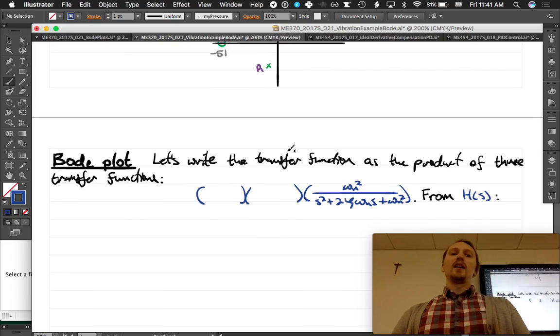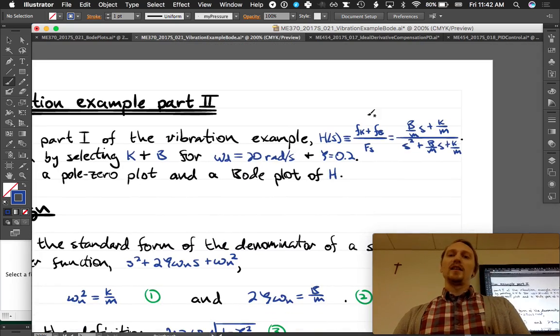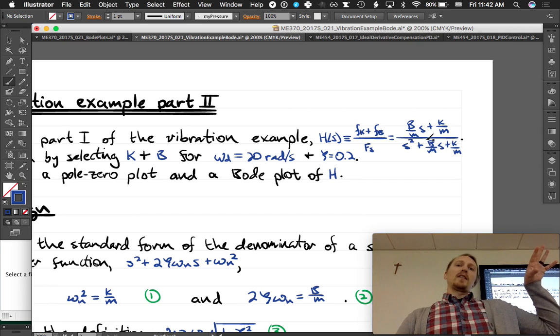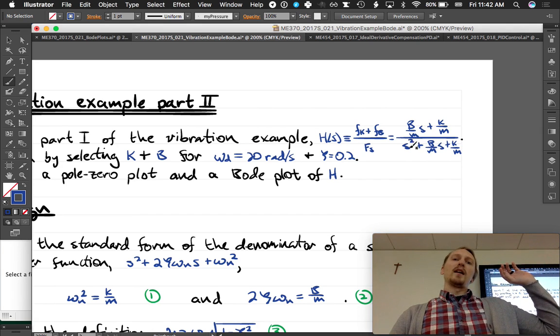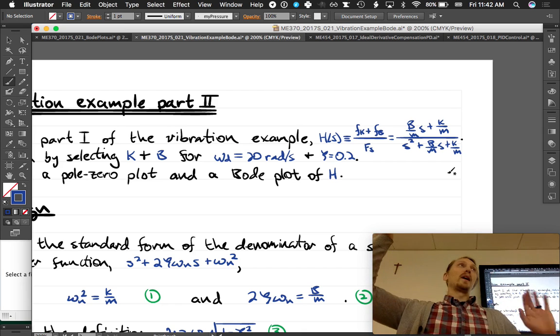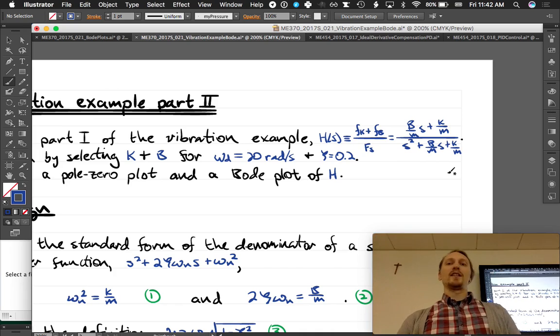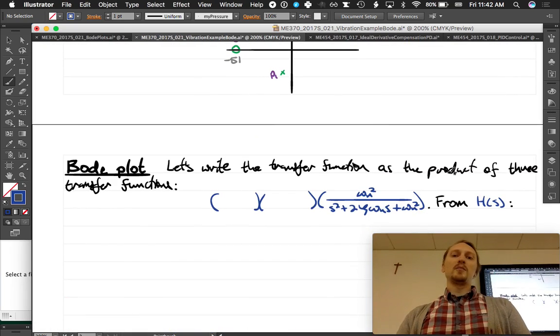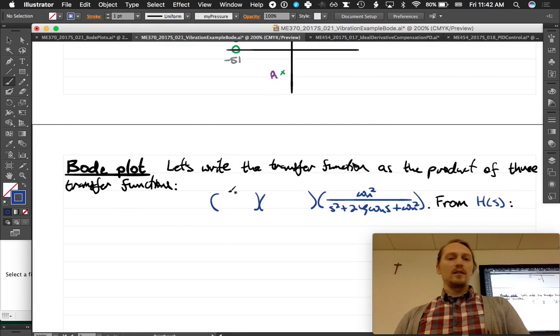If we took this numerator and split it off to a separate term, then the numerator of this fraction is 1 over the s squared denominator. So we have 1 in the numerator. If we want the numerator to be omega n squared, we could just plop an omega n squared in the numerator, but we have to divide by omega n squared somewhere, right? So let's make that division by omega n squared out here in the constant term, because we must do that.